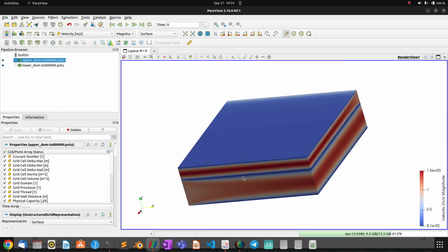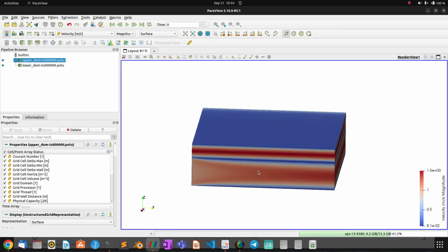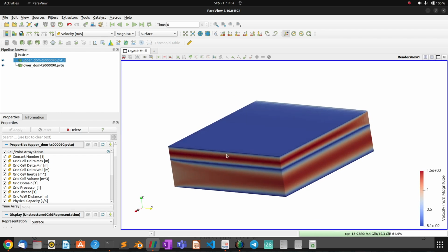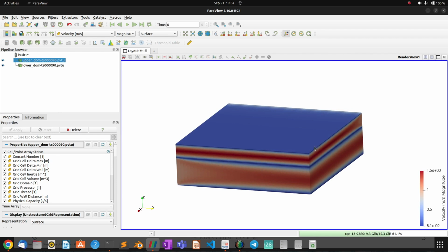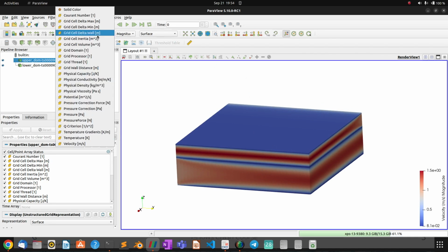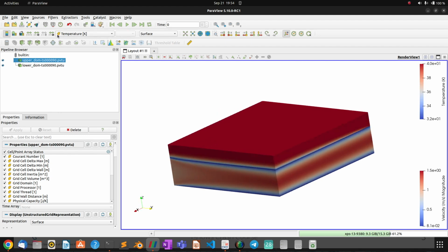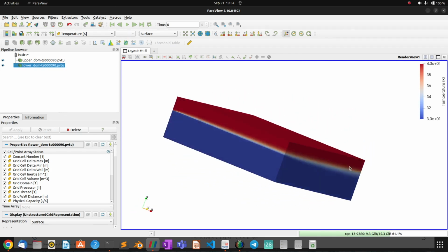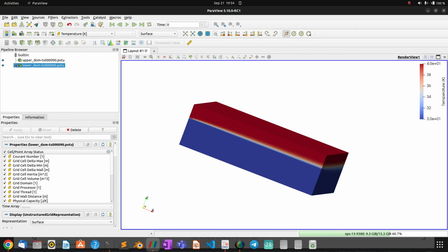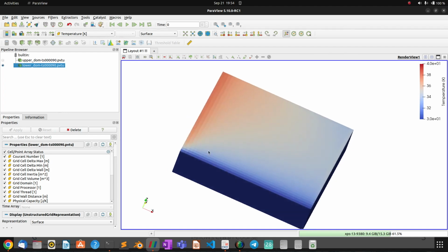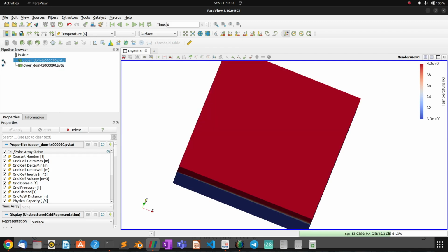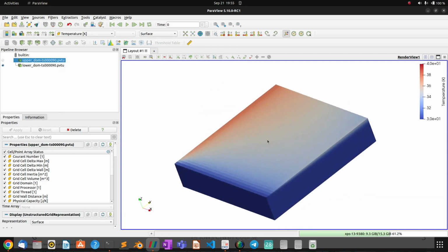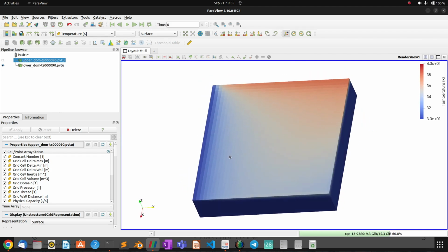And now I'm going to show you how to add the transport of a passive scalar on top of this domain. So let's say we want to use domain 1. Of course, you can always visualize other parameters here. Not sure if here it will show you something like this. Okay, so you can see already, maybe if we switch this off, you can see already that the temperature is being advected, and you can kind of see something. Maybe it's a bit too early, but you can see already that it's a bit swept in that direction, the transport of the temperature between the two plates.